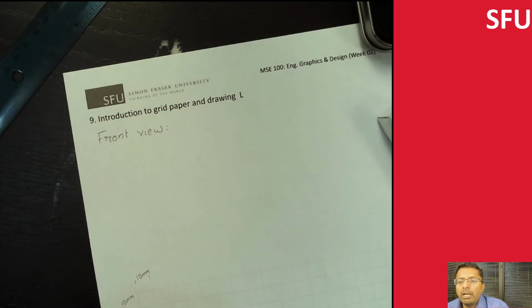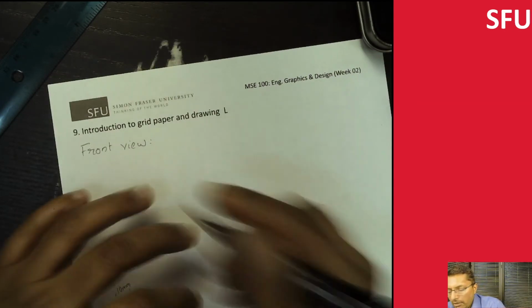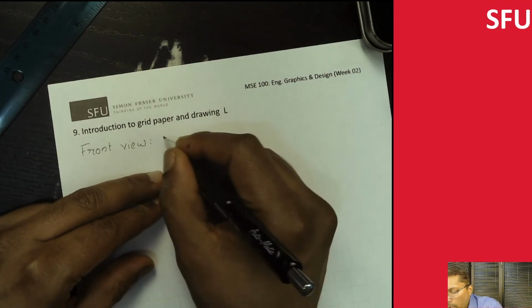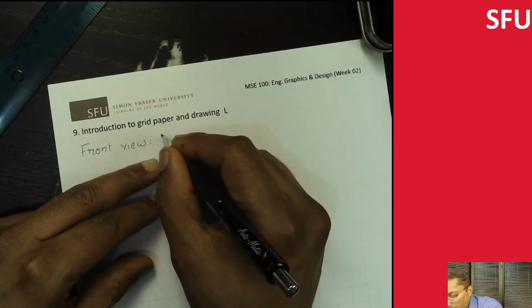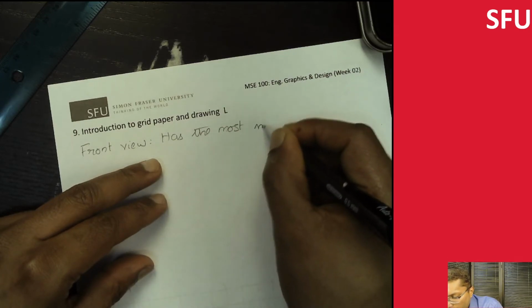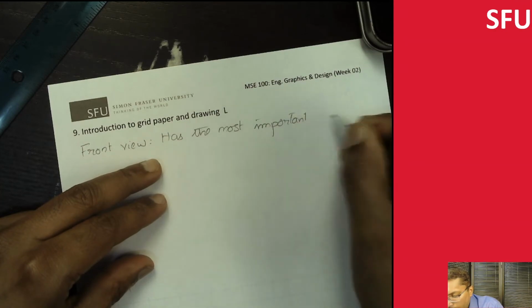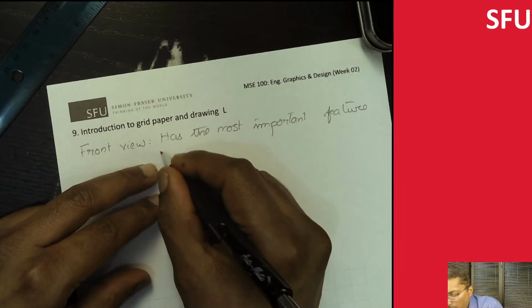So the question then becomes, how do I actually select this particular front view? Generally we pick the view with the most information or most interesting feature as the front view. So typically the front view has the most important feature, or it could have the longest dimension.